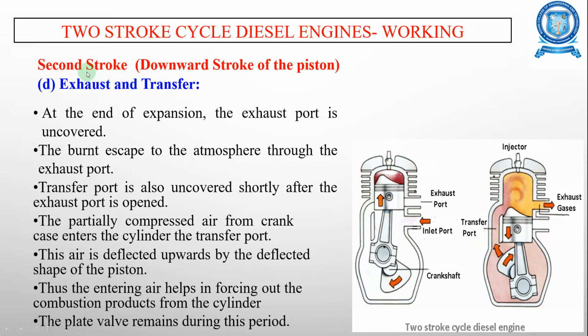Again in the second stroke, the downward stroke of the piston, you have exhaust and transfer. At the end of the expansion, the exhaust port is uncovered.